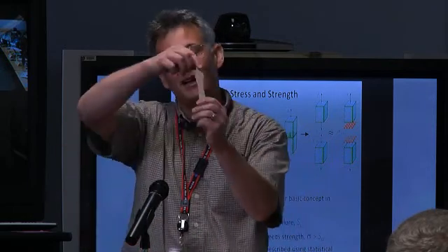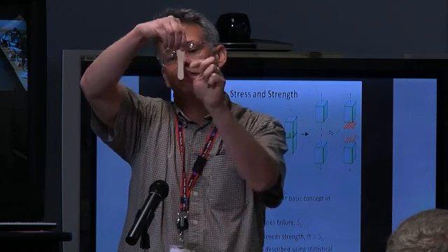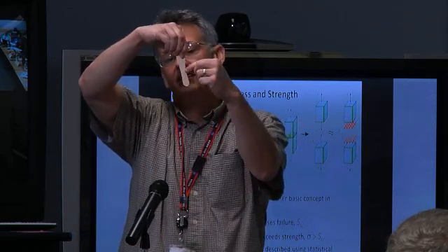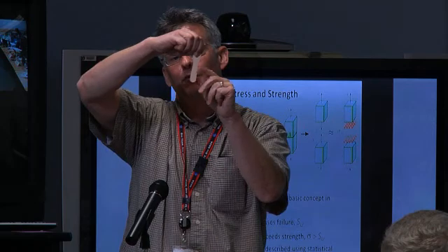But stress is basically a very simple concept. You've got a structure. It's got a cross section, like a length, a width, and diameter. Take that cross section, essentially cut this in half, and look at that cross sectional area. When you pull on that, that force divided by the area is called the stress. It's a concept we use to understand inside a structure what is the mechanical state of that structure. It's basically the amount of force that's trying to be transmitted over any interface. I pull on it a little bit, I've got a little stress. I pull on a lot, I've got a lot of stress. Eventually I can pull on enough and I break it.